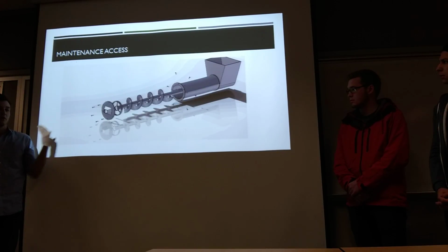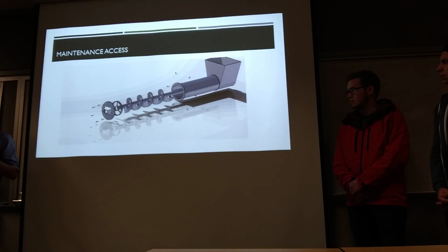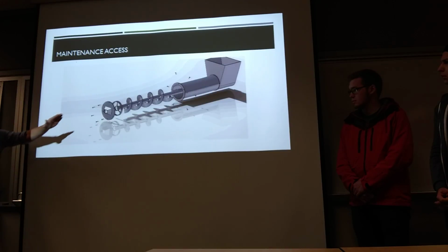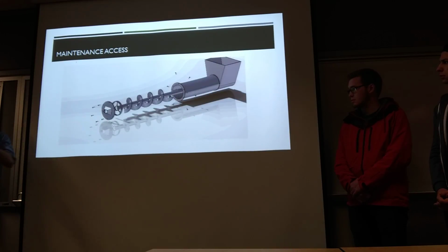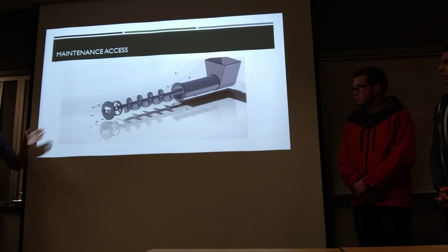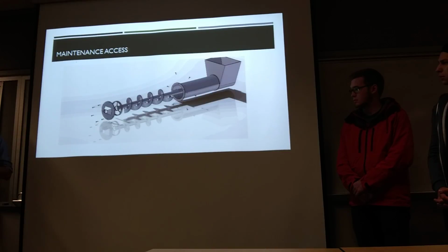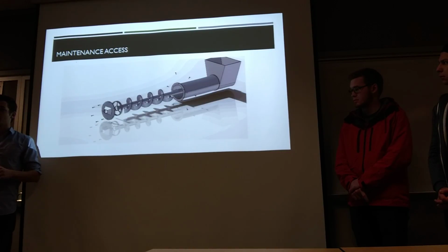The way we want to do this in the front is because we know the power team is going to have the gearbox and the motor on the back, and we want to make sure that we weren't messing with their stuff, so they can just keep that and we can pull it out the other way. Additionally, you'll have the rollers here, so you can easily pull the auger out, and you don't have to have too many people there, and it's not as dangerous. A quick note on the die: I know the die team is using a different way to fasten the die here. Instead, we use bolts just to keep it simpler so our model can run smoother.